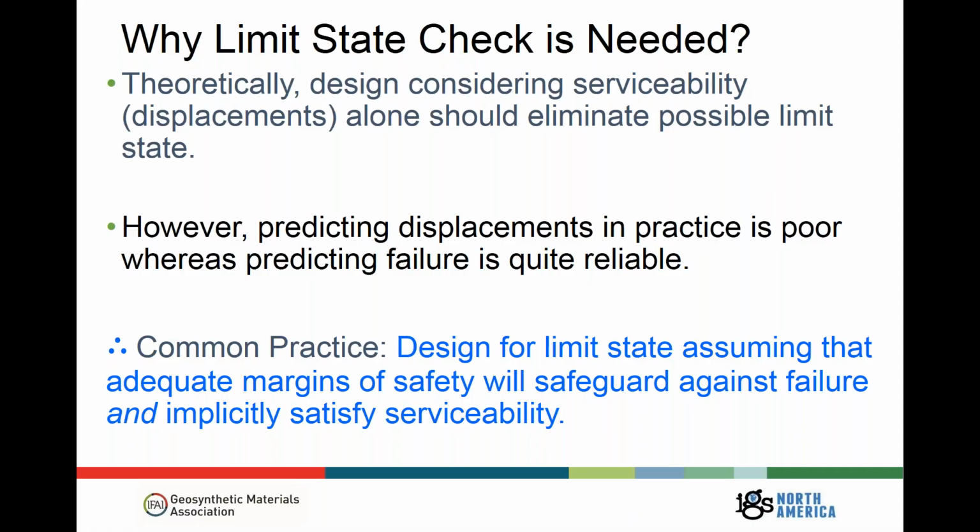However, as we all know, predicting displacements in practice is not a common thing to do, and we're not really able to do it that reliably. However, predicting failure or a strength limit state is pretty reliable and based on statics that have been around for quite a while. So common practice happens to be that design for the limit state assumes that if we have an adequate margin of safety, we can safeguard against any failure, and maybe by virtue of having the conservatism implicit in this, maybe it will satisfy serviceability too.